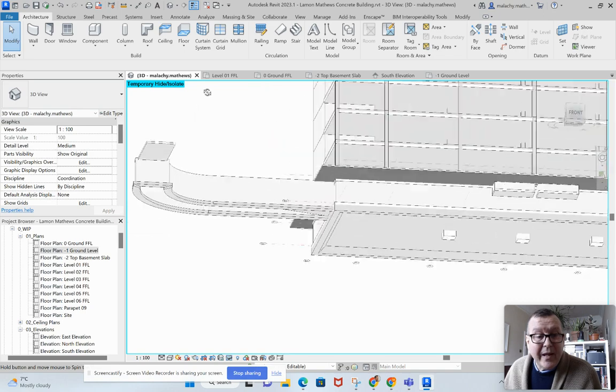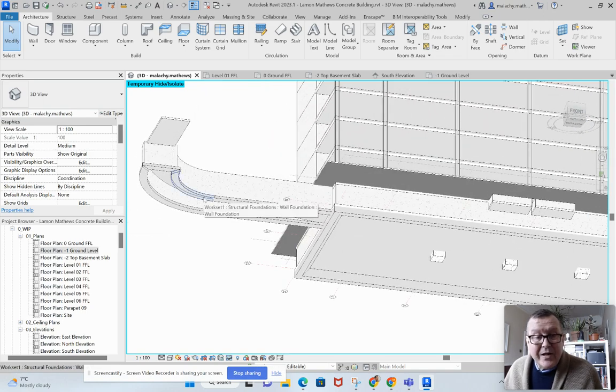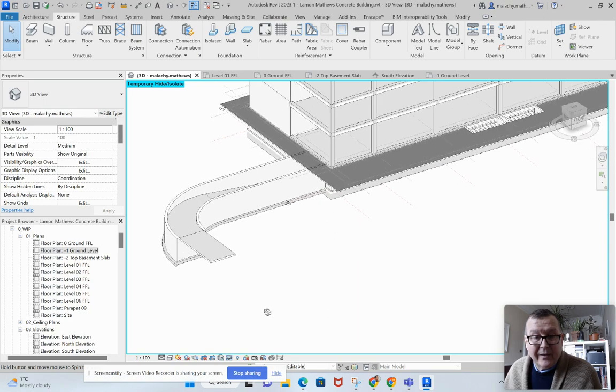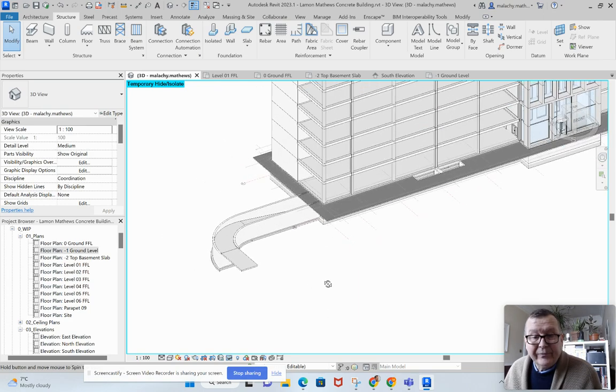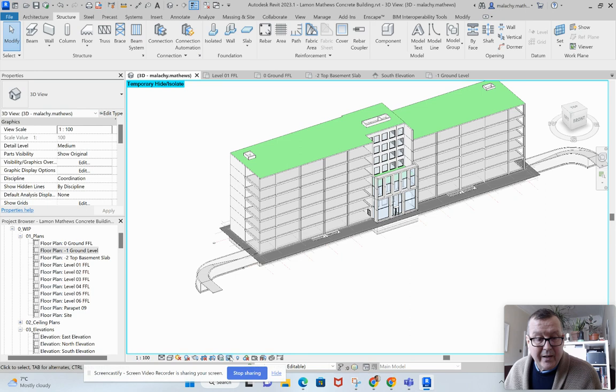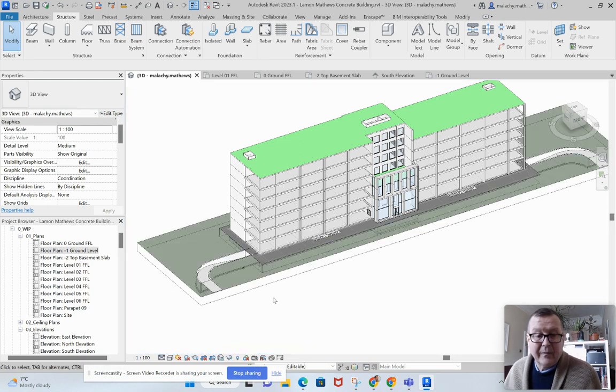I put a foundation underneath these, so structure, and this one here. A standard strip foundation goes in underneath that retaining wall. So that's that element. We've got the path in there, the retaining walls, and our ramps coming out here. And then I'll put back in the ground.